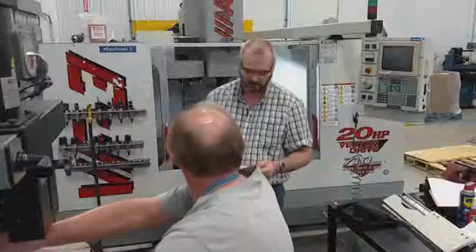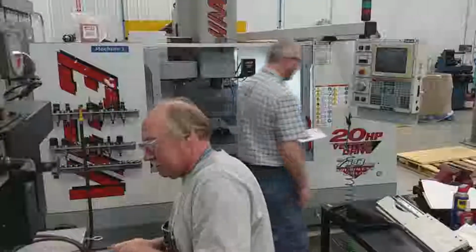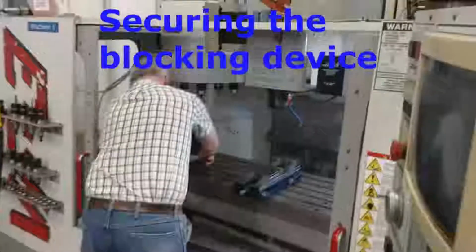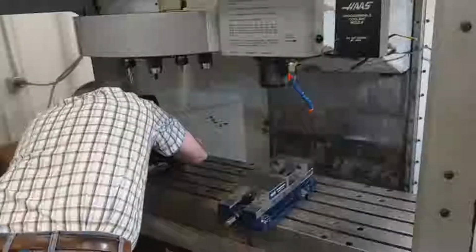Pete, I'm going to be locking out the Haas, so don't mess with it. Okay, Tony. Now Tony's going to install a blocking device that effectively holds the milling head up, thus preventing it from dropping down and crushing him.